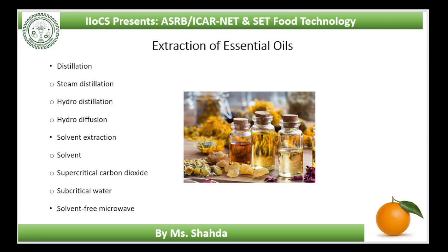Solvent extraction. Conventional solvent extraction has been implemented for fragile or delicate flower materials which are not tolerant to the heat of steam distillation. Different solvents including acetone, hexane, petroleum ether, methanol or ethanol can be used for extraction. In general practice, the solvent is mixed with the plant material and then heated to extract the essential oil, followed by filtration. Subsequently, the filtrate is concentrated by solvent evaporation.